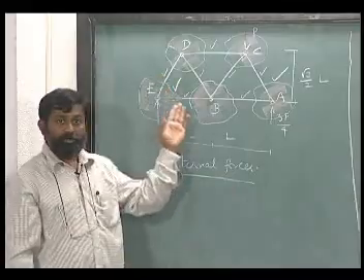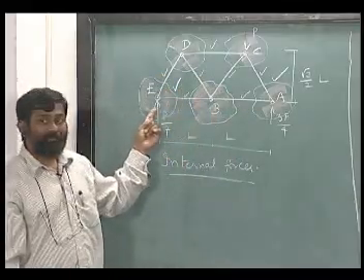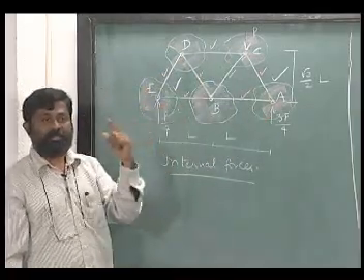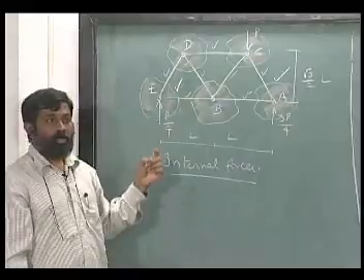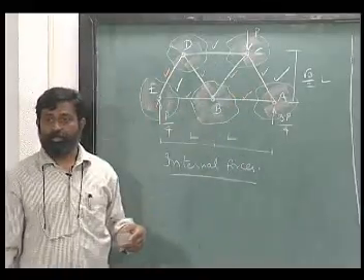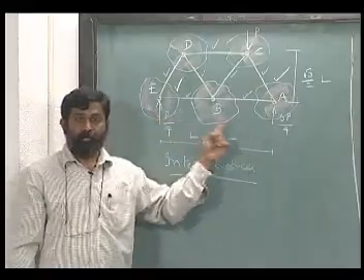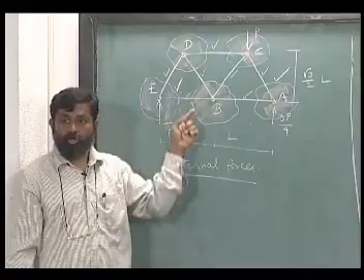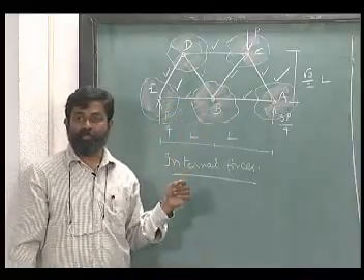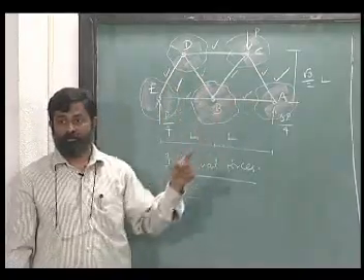I can now start to examine and find out the internal forces by drawing the free body of each of these domains that encircle a single joint, or in other words free bodies associated with each of these joints. After doing that, I will pick the appropriate order of these joints for writing equilibrium equations to solve for the internal forces in these members.